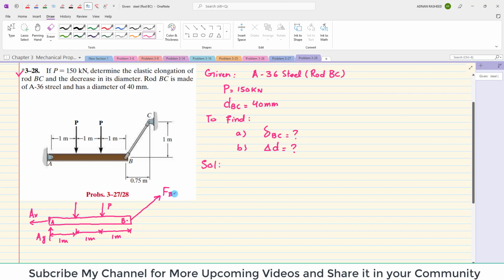Let this force be F_BC. You can see this makes an angle of theta, so tangent of theta will be equal to 1 over 0.75, and theta is equal to tangent inverse of 1 over 0.75, which means that theta is equal to 53.13 degree. Now this force will have two components, one in the horizontal direction and the other a vertical component: F_BC x and F_BC y.